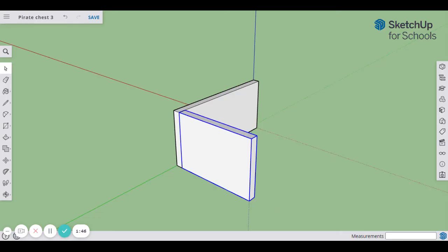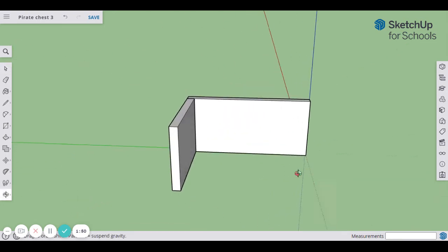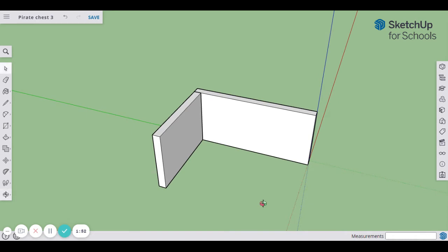So anytime you make a piece in SketchUp, you want to make sure that you make it a component. Students should know that by now. All right, so hit your space bar, select the end piece. We're going to hit M for move and Control to copy, so you get that little plus symbol there. Move, copy, move, copy. There we go. That's with the Control key.